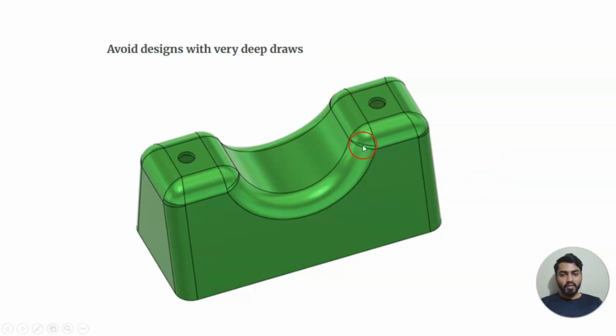Because more curvatures and entire shapes we can't get accurately by using sheet metal fabrication, but in plastics or die casting methods we can get them. Fabrication is nothing but, like, we cut with laser cutting, then we bend. So by bending only we get the shape, or else by using press tools, we make punches. Smaller shapes we are able to get by punching, but intricate shapes we can't get.